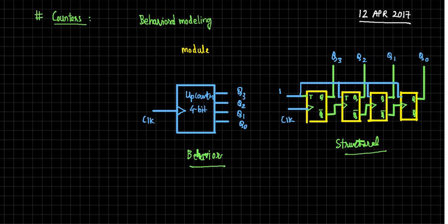If I ask you to define this 4-bit positive edge triggered up counter, how will you define it in one line? As the next positive edge of the clock appears, the count will be incremented by 1. That is the single line description in behavior. In structure, we'll have to define what flip-flops to use, how the connections are made and so on. Let's go for design in both ways. Let's go for behavioral first, just because it's quite simple.